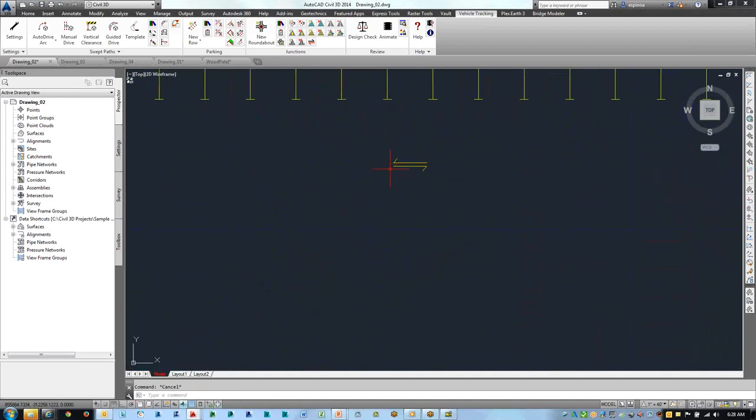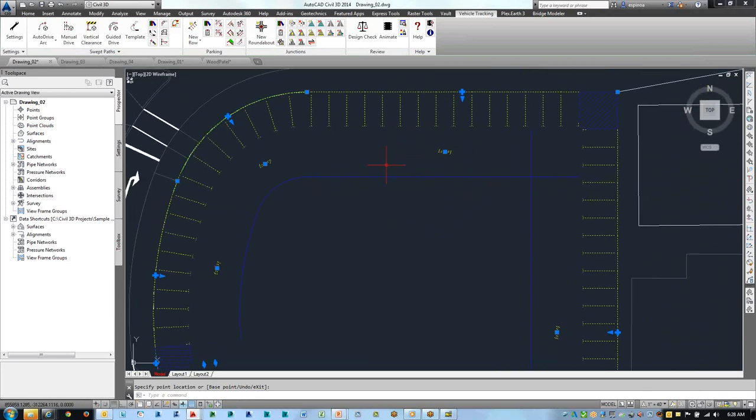One is that I see that in this area in front of the stalls, it's expected that we have 2-directional traffic. If I select the entire object and grab that particular grip, I can change it from one direction to the other direction or to 2-direction. And we see this blue guideline here. That changes based on the direction of the cars that are coming in, so that we have that understanding of how much clearance would typically be necessary in order to pull into any of these stalls.